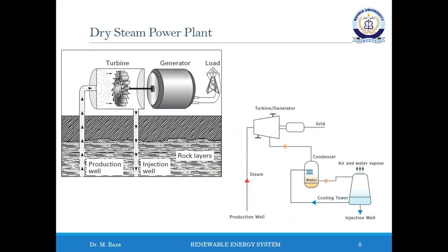The choice of the heat exchange and turbine system for a particular geothermal source is complex, requiring specialist experience. There are four main types of geothermal energy conversion system. In all methods, nearly always the emerging bore water after use is re-injected into the reservoir. The simplest system passes dry steam from the ground directly into a steam turbine as shown in the diagram.